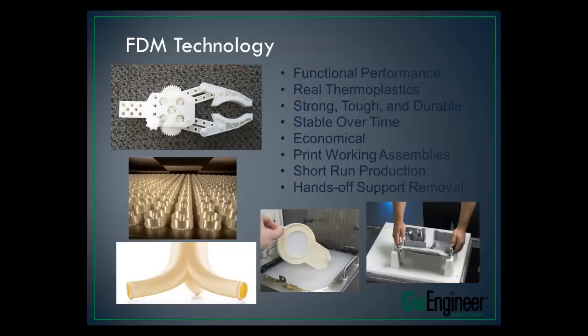That means the resin, the material they're actually spraying or extruding, is not actually ABS, but the properties are close to it. With FDM technology, you get that actual plastic, ABS, polycarbonate, Ultem, which means it's very sturdy. The chemical properties are very easily found in reference manuals.